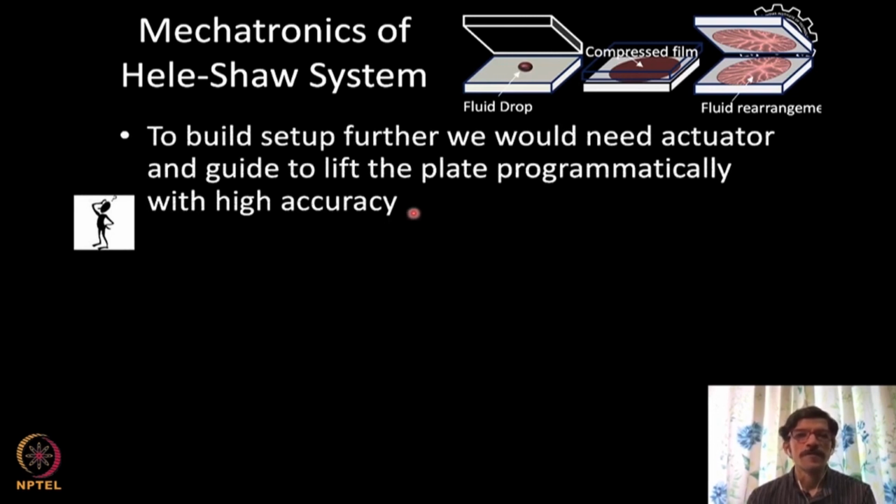We can use some kind of a ball bearing for the straight line guide. That also may work, but we are using other kinds of compliant mechanisms to reduce friction in the system, and this compliant mechanism is based on spiral grooves in a small disc.